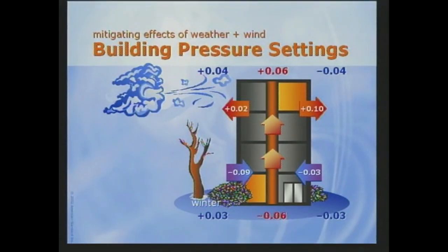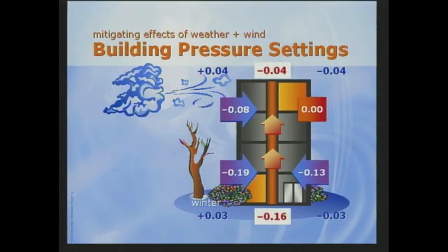For tall buildings in cold climates, wintertime stack effect can cause significant positive pressures at the upper floor. In our example 4-story building, top floor exfiltration can be eliminated by lowering overall building pressure by 0.1 inches. This takes a ground floor pressure of at least negative 0.16 inches.